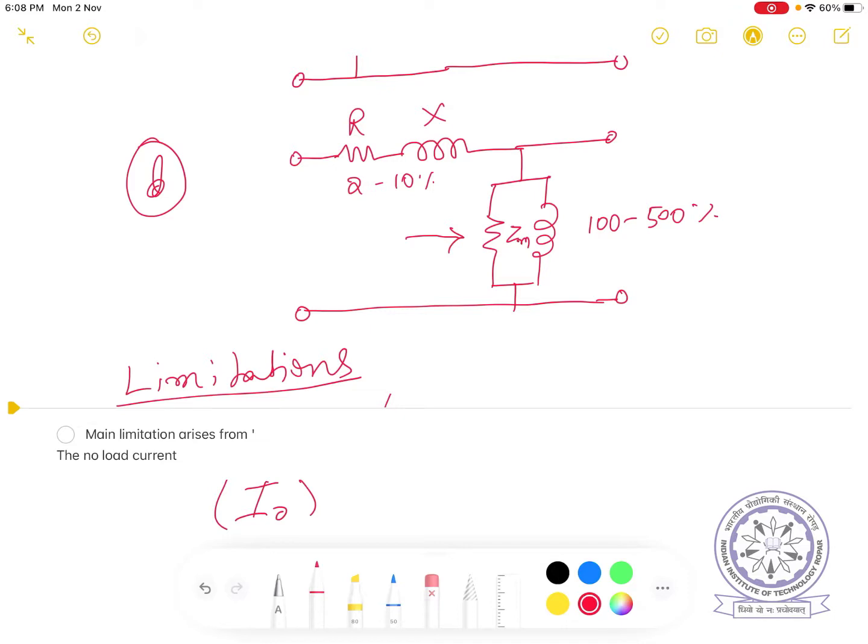So the RC here is represented as dissipating the same amount of power loss that is occurring inside the core. But it is not physically a resistor that exists inside the core and dissipates that power. Therefore, it is to be remembered that this is not a physical resistance.